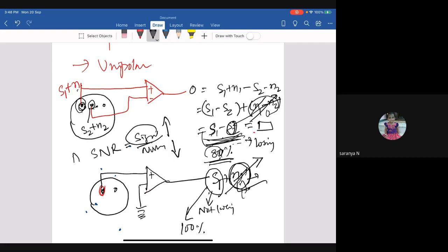But the doctors mostly use EEG to detect, let's say, spikes, seizures, or epilepsy. For that kind of activity, this is a powerful method. But for many other cognitive processes, they will lose much information, right? But as I told you, if you are doing research to understand brain function, go with the unipolar mode of recording. In that way, you can preserve as much information as possible in your signal. I hope this is clear to all of you. If you have any doubt, please ask me.